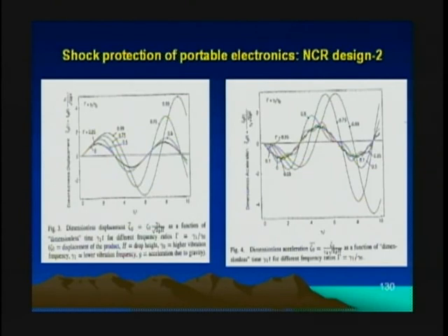And certainly, we want to avoid a rigid impact. So we want to avoid a situation when the vulnerable element goes down under resonant conditions, and you know the resonant conditions result in the difference in phase between the excitation force and the triggered vibrations being 90 degrees.